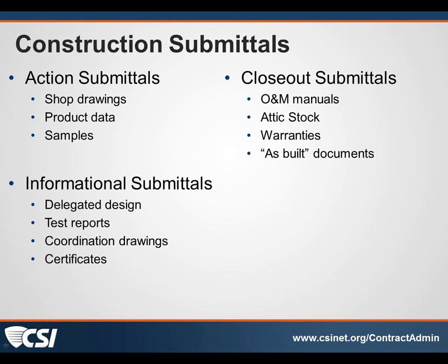Mohammed has a question here. What about RFC, or requests for clarifications, as informational submittals? I don't know that I've ever used the term RFC. Jim, I don't know if you have or not. I want to comment on that. If a contractor is asking a question for an interpretation of the documents, then it would be an RFI, and that's totally different.